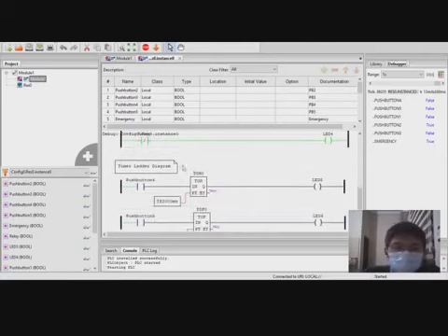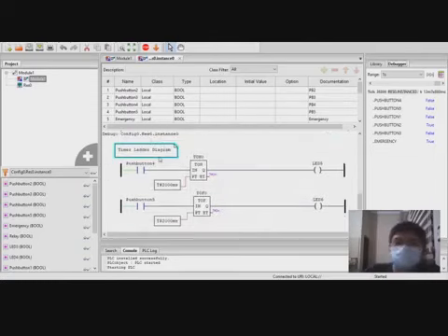And then we move to the timer ladder diagram. We have here the push button 4. Let's see what this timer does. This is a timer on, and for example we give a time value of 2000 milliseconds. Give a true value. After 2 seconds, the LED will turn on.